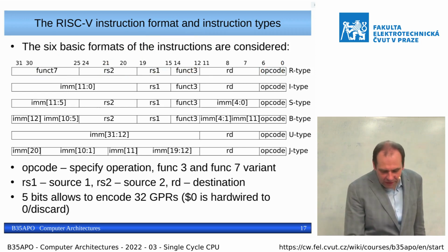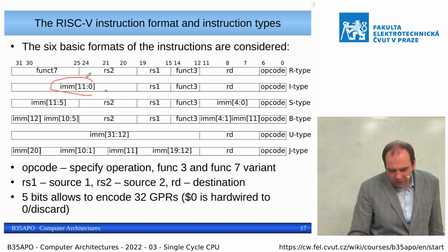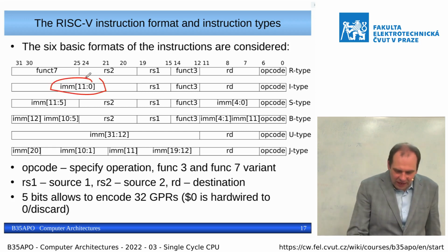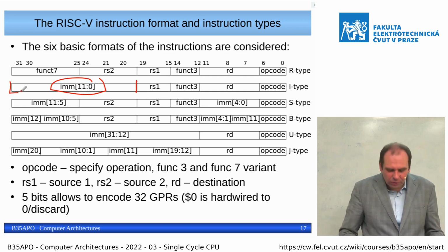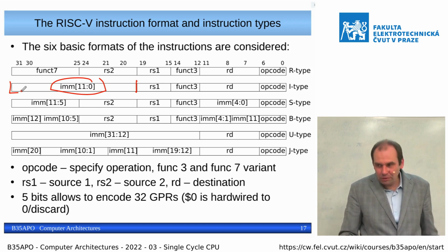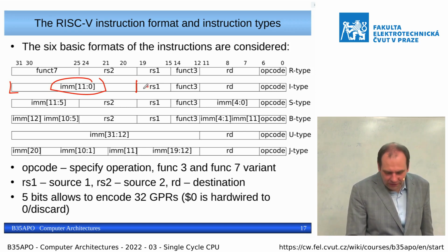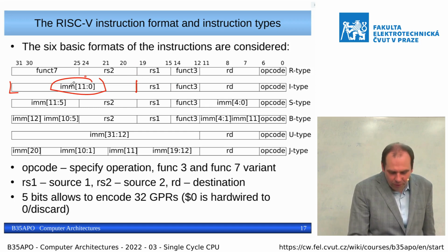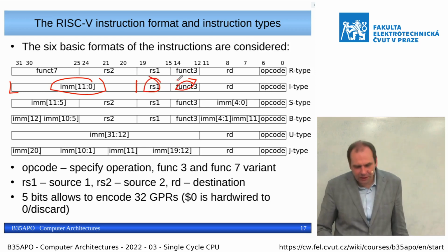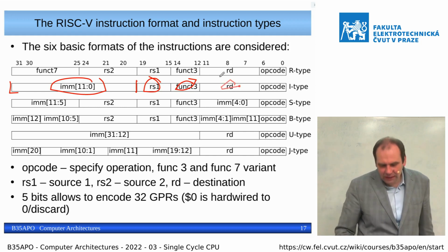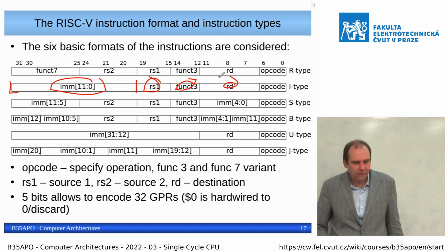At the moment when we want to add the immediate value, they decide to keep only 12 bits, because the code space is quite small, and to put the data inside is a problem. So they decide that they have only 12 bits of immediate operand. They keep the position of the source operand. Function says if it is addition, subtraction, and so on. And we store the result into the destination register. Still clean and relatively well readable.